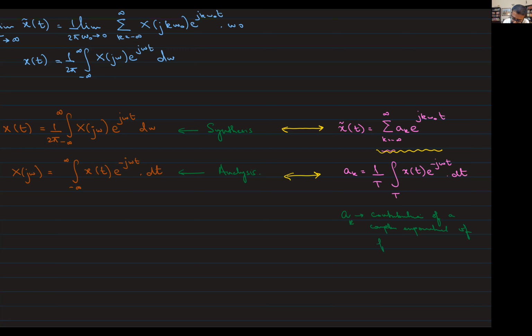And that led us to the frequency domain analysis, where, as I think Umar pointed out, the square wave had lower magnitudes at high frequencies and higher magnitudes at low frequencies. That let us visualize that signal in a different manner, with a different perspective, right? That the high frequency components have lower magnitudes and the lower frequency components have higher magnitudes.